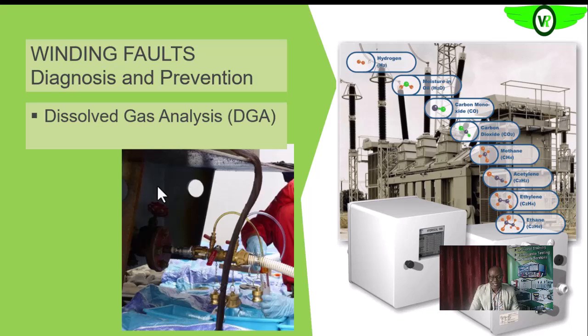Remember, the oil is made up of hydrocarbons, okay? So it depends on what is happening within the winding as it is heated up, either by virtue of its normal operations, or when there are fault conditions like arcing, shorts, or overheating due to excessive current flowing through the transformer windings. All of these can cause the decomposition of those hydrocarbon molecules within the transformer oil. On dissociating, the product of dissociation is determined by the kind of fault that is within the transformer.